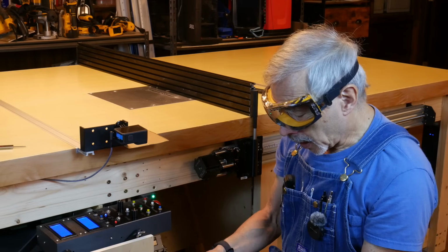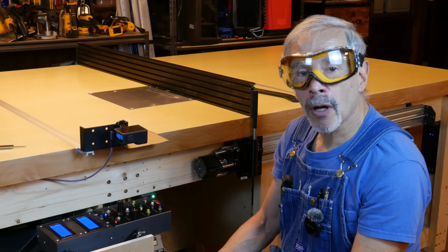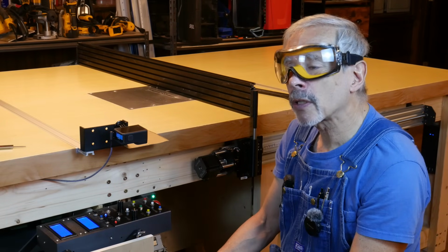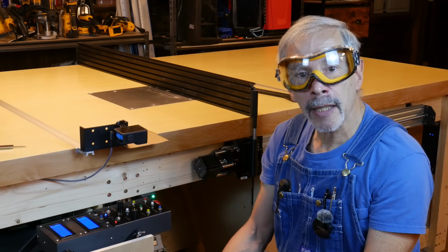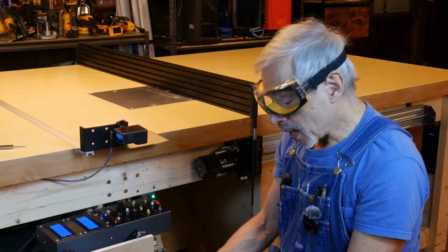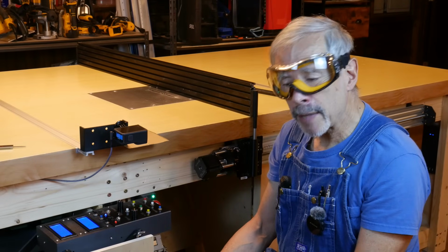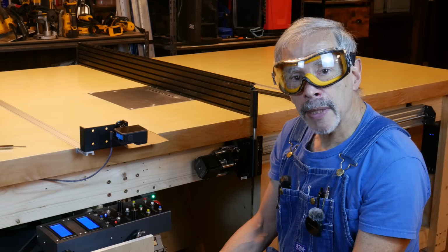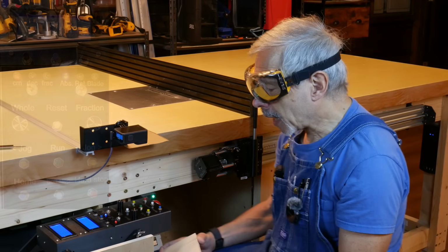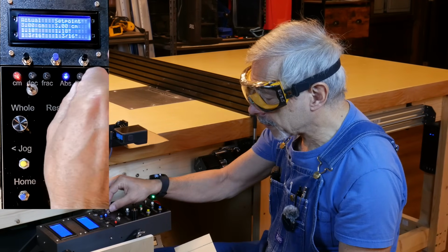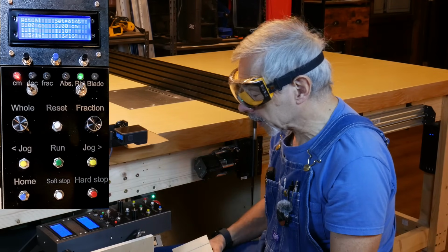The first cut has the width of the saw blade, which is about 2 millimeters. And if I want a dado exactly 8 millimeters, then I have to do 3 more cuts 2 millimeters apart from each other. And to do that, I'm going to use the relative feature in the system.